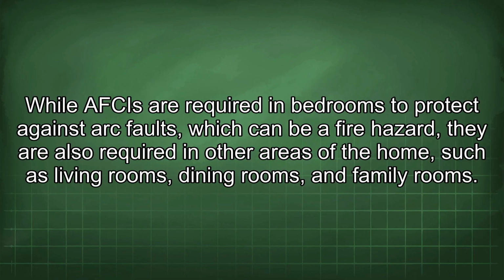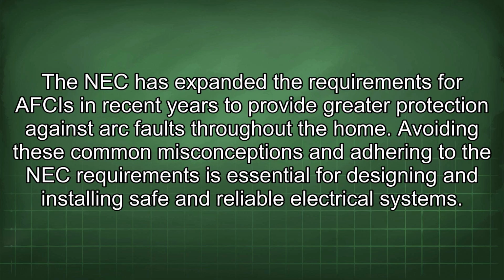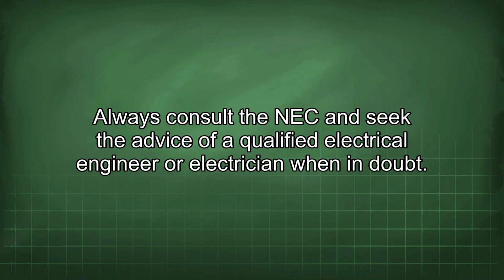Fifthly, there is a misconception that arc fault circuit interrupters, or AFCIs, are only required in bedrooms. While AFCIs are required in bedrooms to protect against arc faults, which can be a fire hazard, they are also required in other areas of the home such as living rooms, dining rooms, and family rooms. The NEC has expanded the requirements for AFCIs in recent years to provide greater protection against arc faults throughout the home. Avoiding these common misconceptions and adhering to the NEC requirements is essential for designing and installing safe and reliable electrical systems. Always consult the NEC and seek the advice of a qualified electrical engineer or electrician when in doubt.